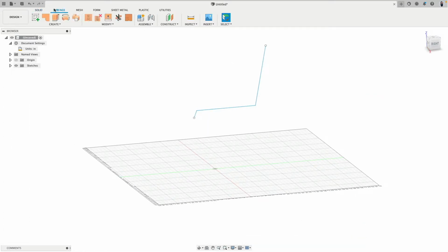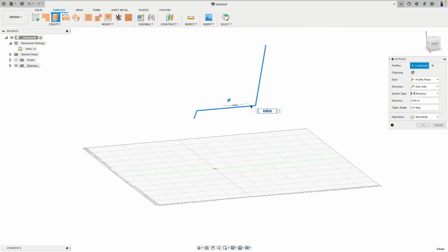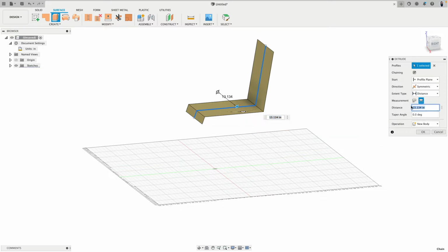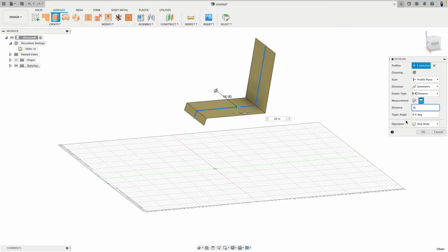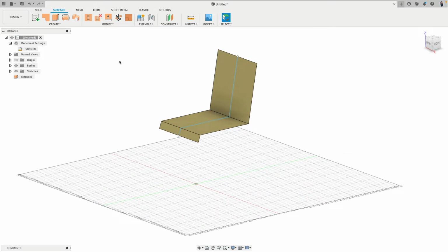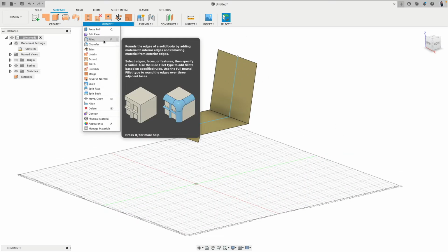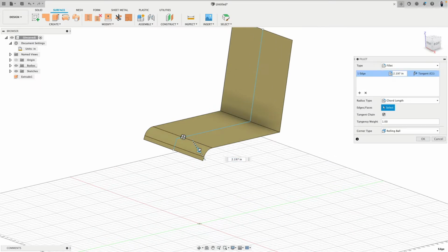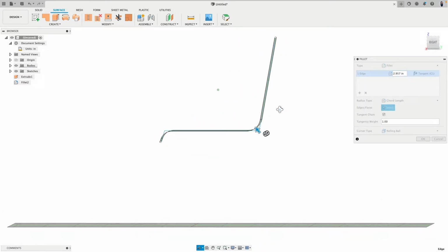We can do a quick study first. Surface, extrude, and then we extrude this symmetry to a total length of 16 inches. Okay, yeah, that makes sense. Everything is very linear. That is done on purpose to make this video a little bit shorter. But some of these corners, as you can see with the fillet tool, we can later also round.